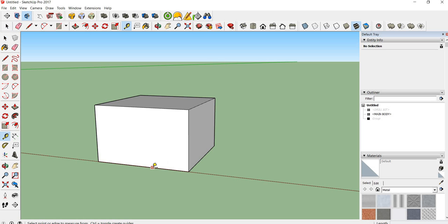So we notice that from here to here is 6615.86. Now, if I wanted to, if I hold Control, and I click, and then I type in 6615.86, and I put mm for millimeters, or quotes for inches, and hit enter, it's going to ask, do you want to resize the model? And you hit yes, and it will resize it to the current size. So I'm just going to do it as 6.615 millimeters. So I just type that in, bottom right hand corner. It's cut off a little bit due to the screen capture software.